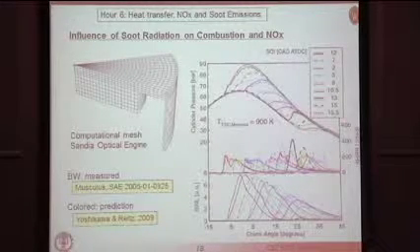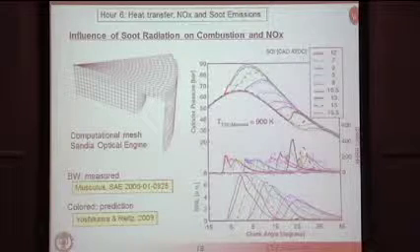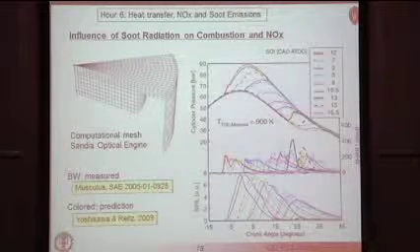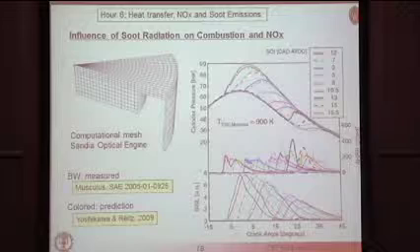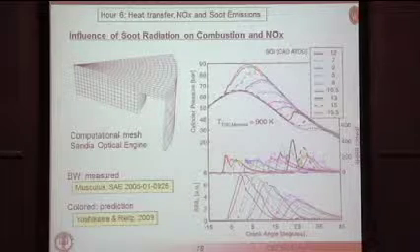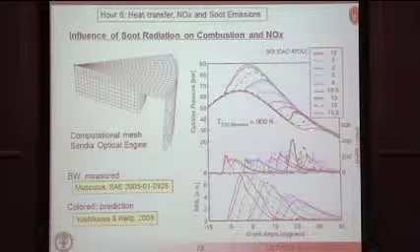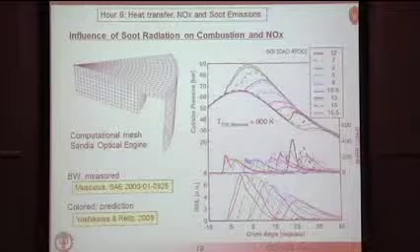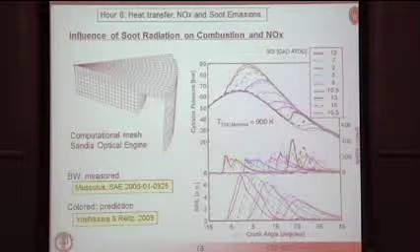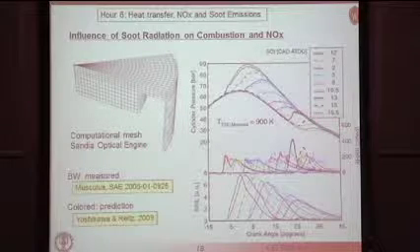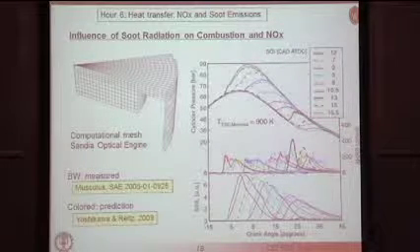But I'm also showing you here Takeshi's simulation results. You can see we're able to match the data; the colored data are the predictions, and the solid lines here are the experimental data. We were able to match over this wide range of start of injection timings, going from 12 degrees before top dead center all the way to 15 after top dead center. So that was encouraging.